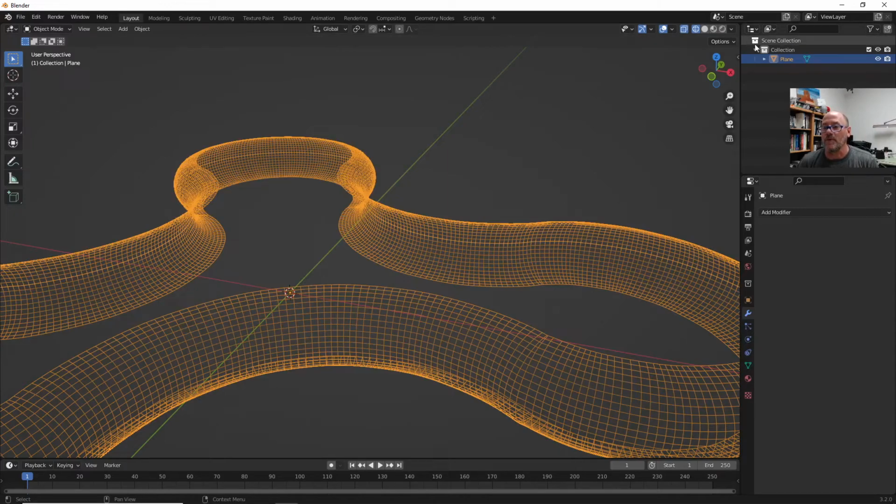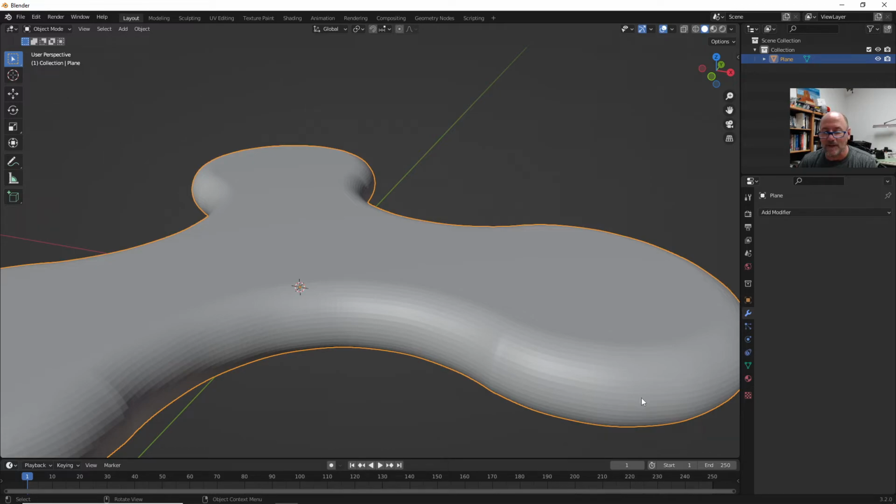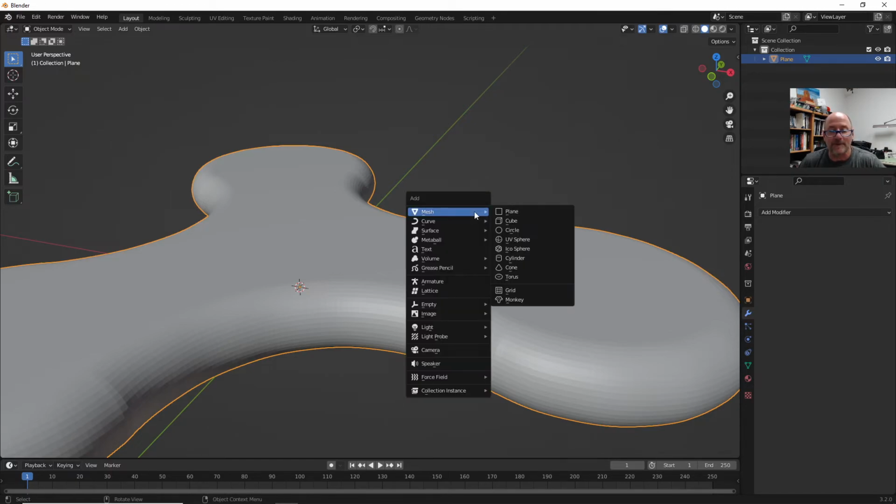Okay, now I'm going to put the holes in it, right? I want to for the bearings and the counterweights. So let's go back to here. And I'm not worried about the facets here. That's just the smoothing algorithm that it's using. And maybe this does point out that maybe I didn't get my vertices quite smooth enough, but we'll just leave it. Okay, I'm going to add Shift A cylinder now.